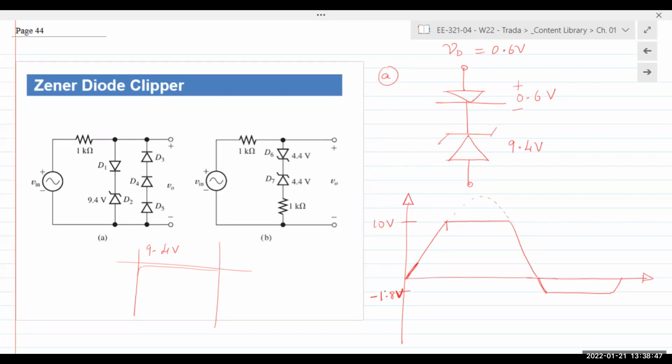So each forward biased diode will require 0.6 volts. Yes. We always have the 0.6. Well, it'll be given in the statement, either ideal diode or how much it's required. So in this case, VD is given as 0.6 to turn on the diode in forward bias. Yes. The 1 kilo ohm resistor will also have a voltage drop. So if you take VO and you connect it here, then you have to calculate what the current would be and then determine it from there.